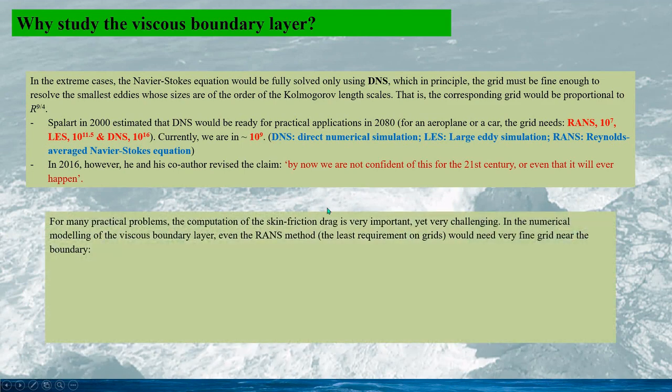We know that for viscous flow, an important aspect is to calculate the skin friction drag accurately, which is a challenge so far for numerical modeling. The most popular method, LES modeling, which has the least requirement on grids, would have issues with grid generation in the boundary layer.